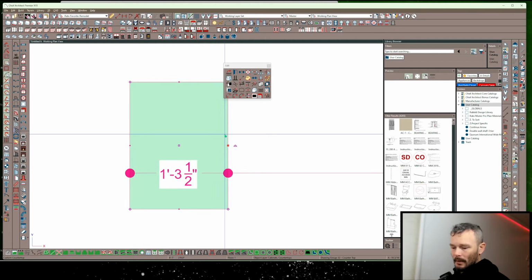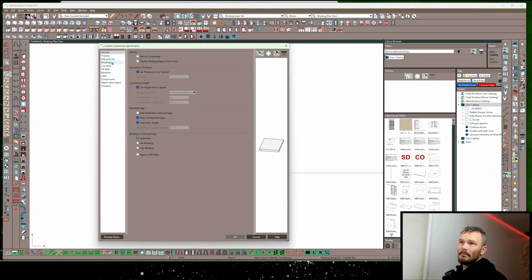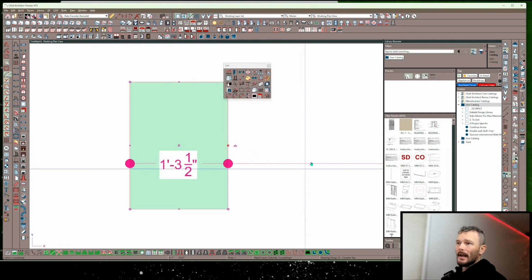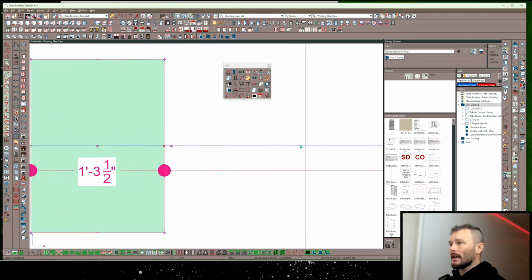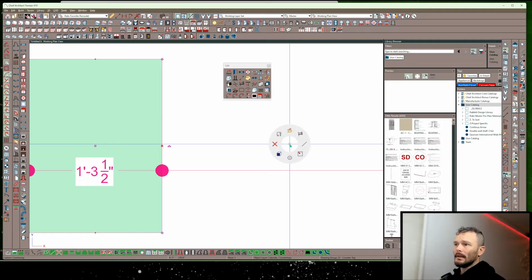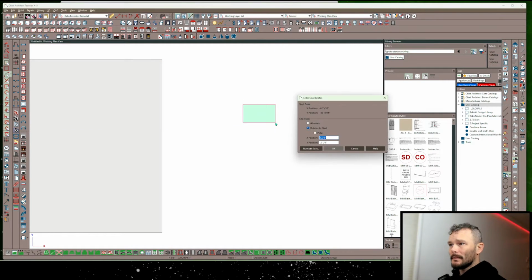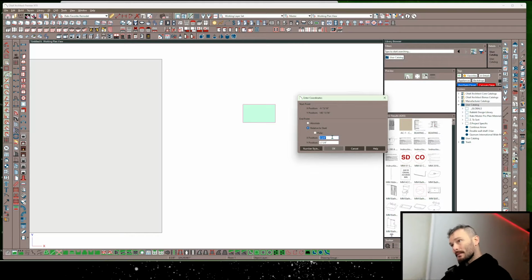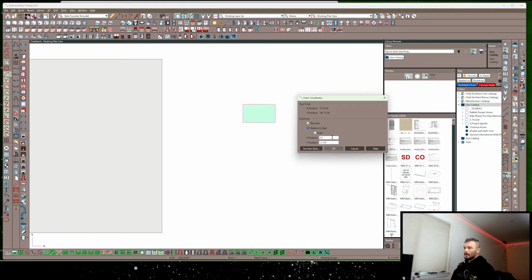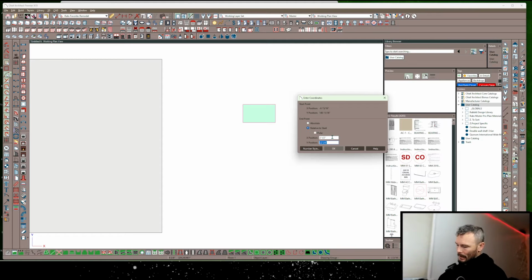And then the next thing I want to do is I'm going to add a molding to this, okay? But before I add a molding to this, let's draw that molding out. So let's use the Polyline tool to draw this out. I'm going to draw out a polyline, and same thing, tab input method, polar is unchecked. So X position in this case, 2.5 inch molding. Y position, let's just say that this is going to be a 3/4 inch molding.